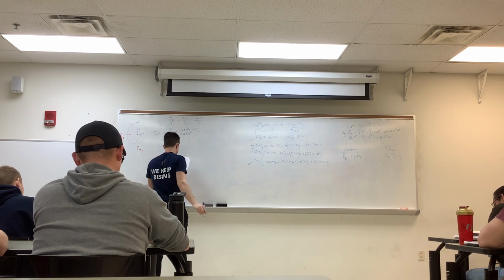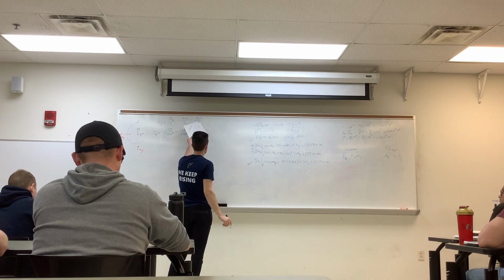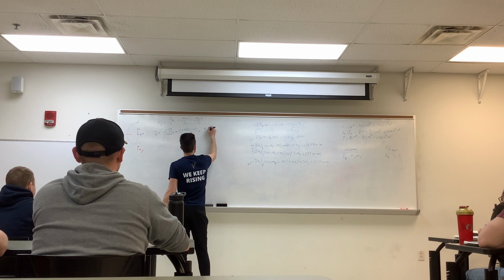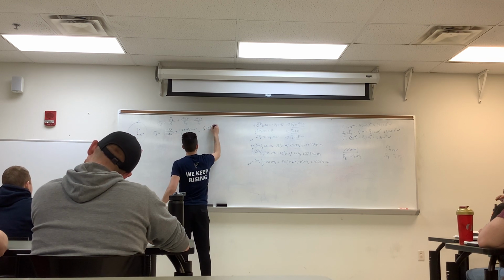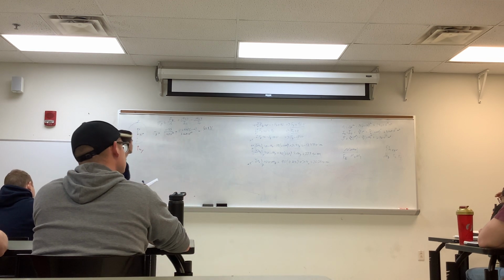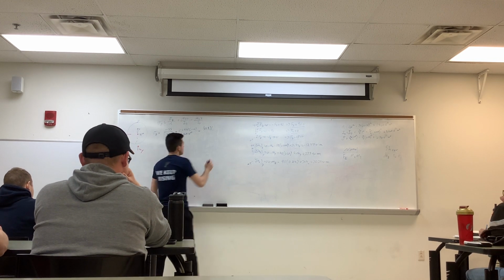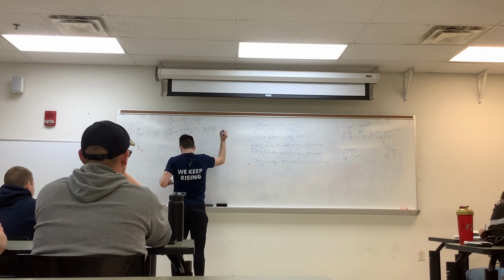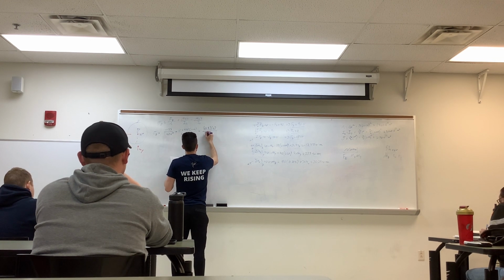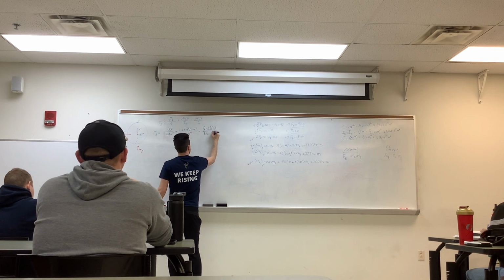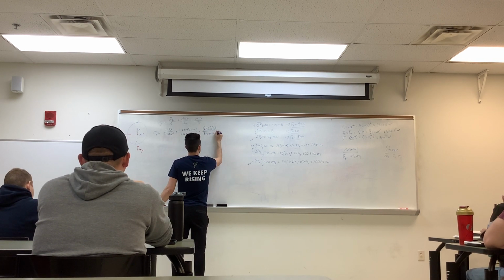And then similarly, the last one we have is a moment about the y-axis, which is 22.5. The distance in the x direction to point H is 0, because it's actually acting about the center here. So we have 0, and we have that as I_xy, I_yx equal each other, 3.068 times 10 to the negative 7th.